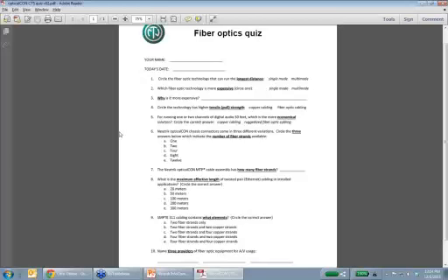Is there such a thing as an MPO to MTP adapter? Well, they're the same thing, so no, they are the same. But in the opticalCON world, specifically, just stick with the MTP Elite line. Stick with it, and you'll be guaranteed to have things work. We always have to worry when we work with this stuff. It's also true with our etherCON products. There's stuff out there that's just not of good tolerance, in the XLR and quarter-inch world as well. I don't want to demean any other companies, but we've had success by sticking with U.S. Connec's MTP Elite line, and we're not alone in that. A lot of other companies have made that decision because the tolerances are just always perfect.